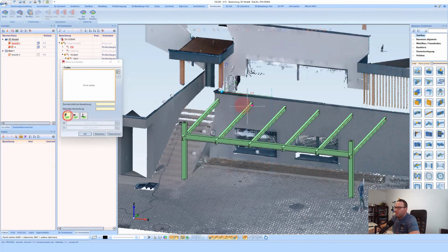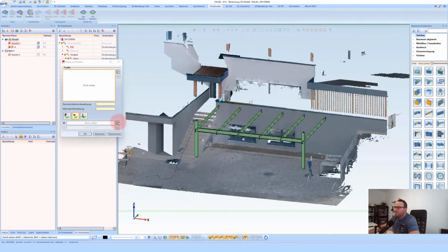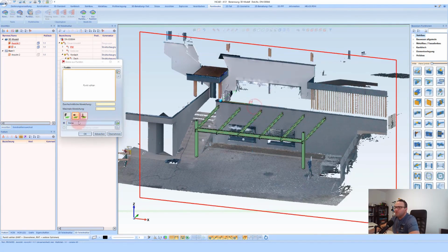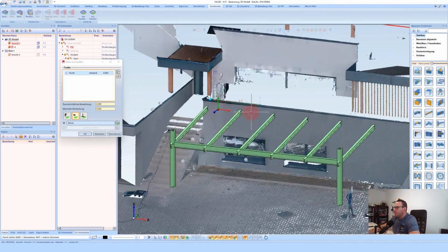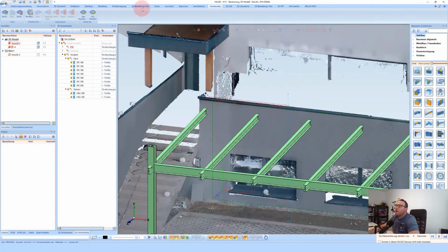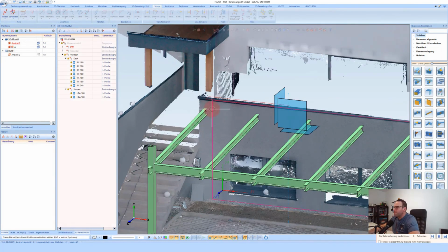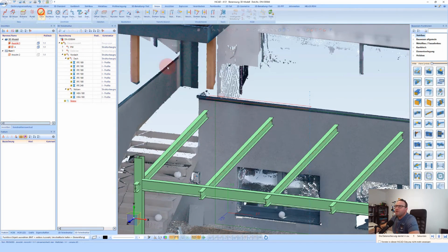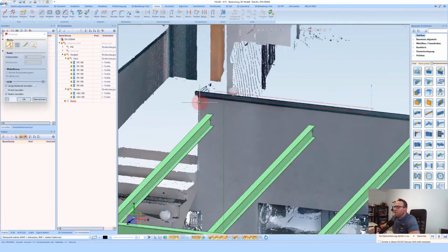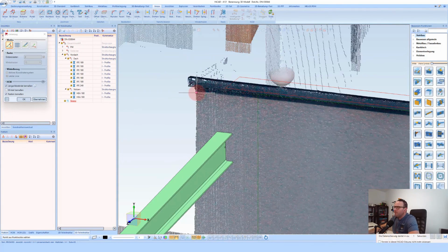I say it should now be freely chosen because, let's try to make it a surface. That means I should be level with this surface, and I just select a few points. Based on this deviation, I see that I am actually quite level here. So 1 mm, which is basically almost nothing. I can easily take the points here with my sketch functions. I take a polyline and simply select these specific points.